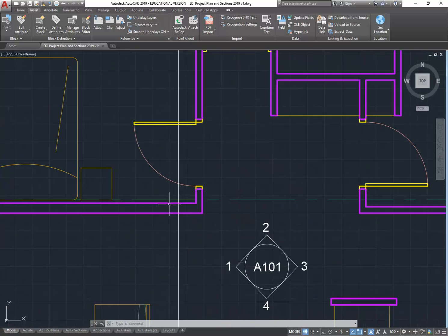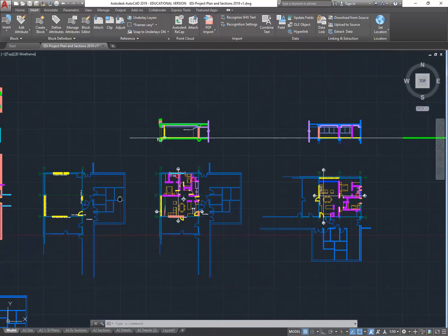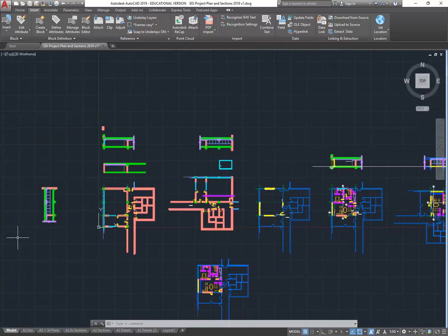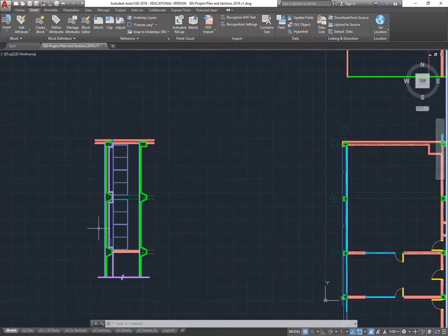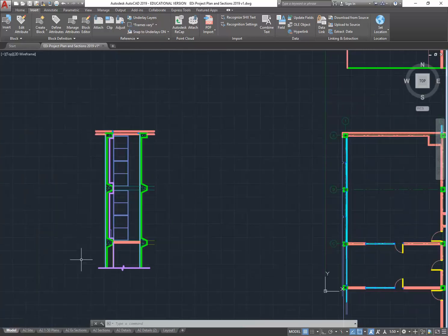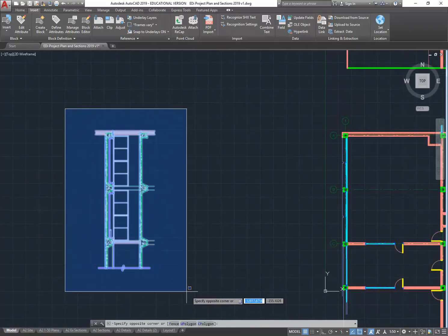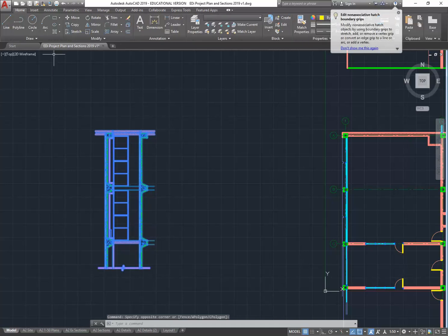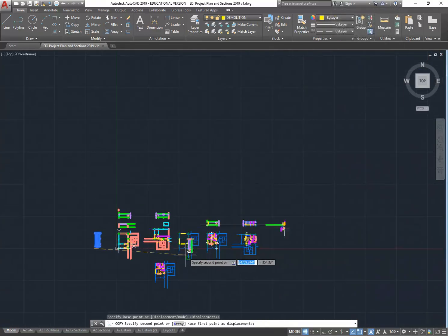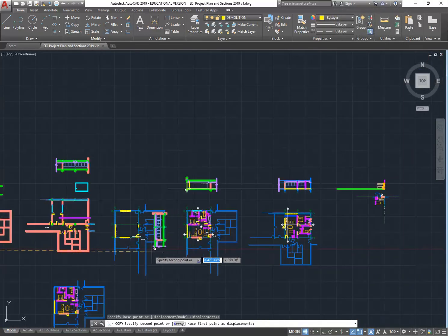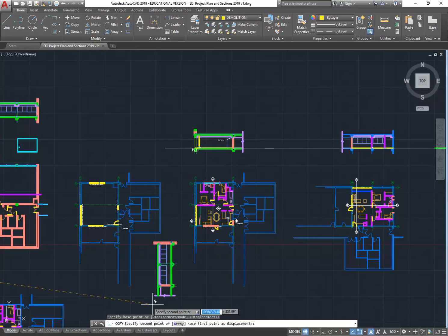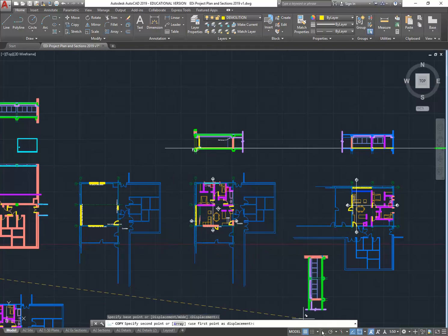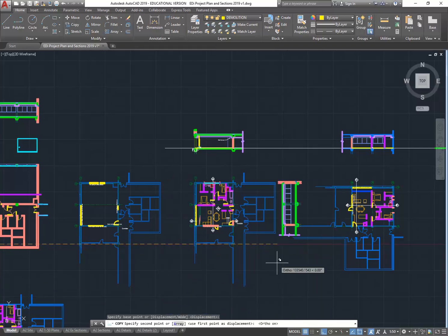And so that you can see, I've got the proposed wall there that will be cut through in a section. And so coming across all the way here, I've got the existing section. And so I want to leave that alone and copy it. So I'm going to leave that there, but then copy it to a place that's convenient to work. And it's getting a bit difficult because everything's tight together. So I'll turn ortho on, so it comes across in a straight line.